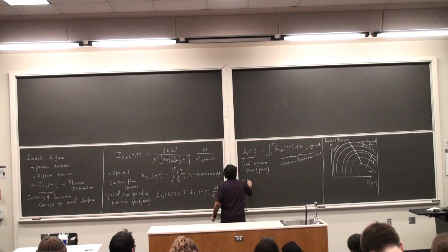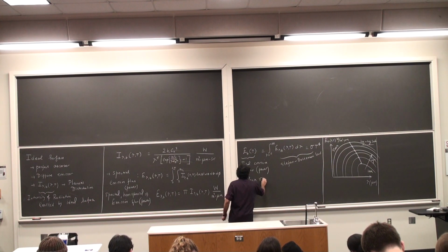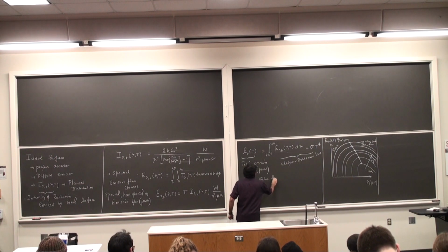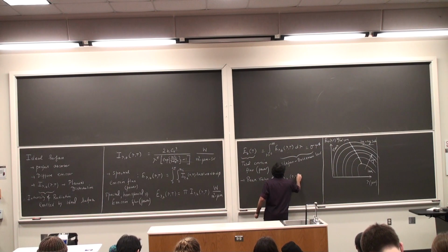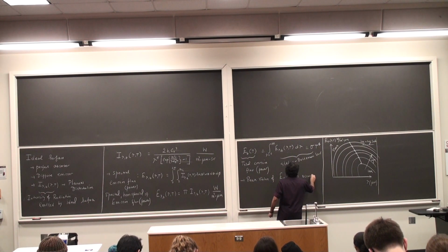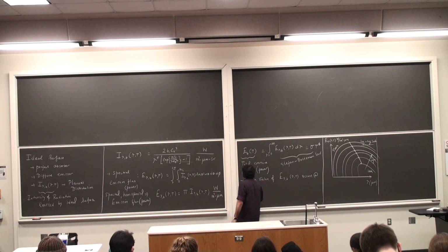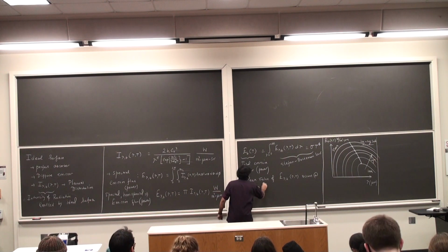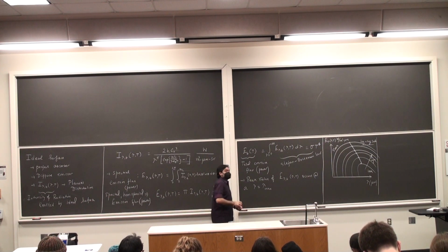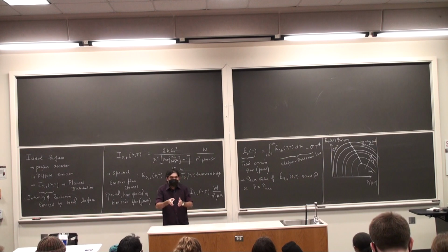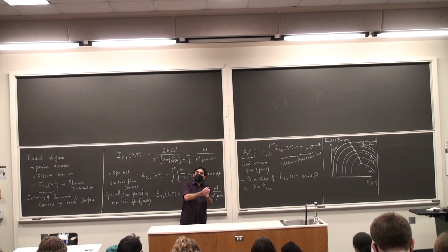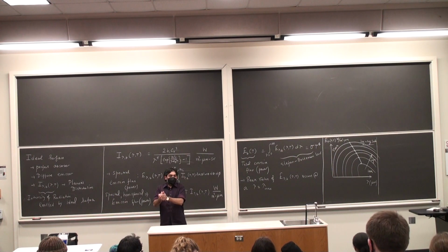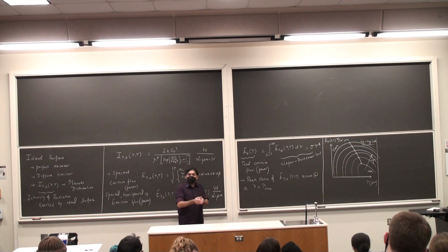So the peak value of E of lambda comma b occurs at lambda equal to lambda max for a given temperature. So for a given temperature, lambda max is going to be a particular value. If I increase the temperature, lambda max is going to start reducing because the values are shifting to the left. Okay?